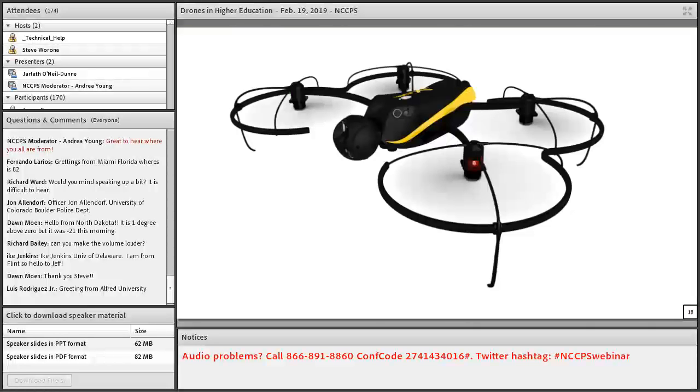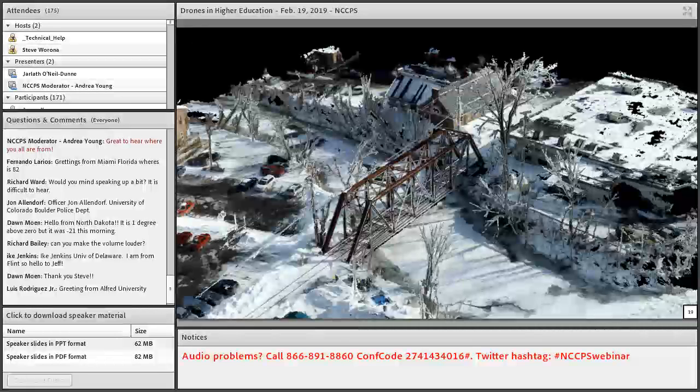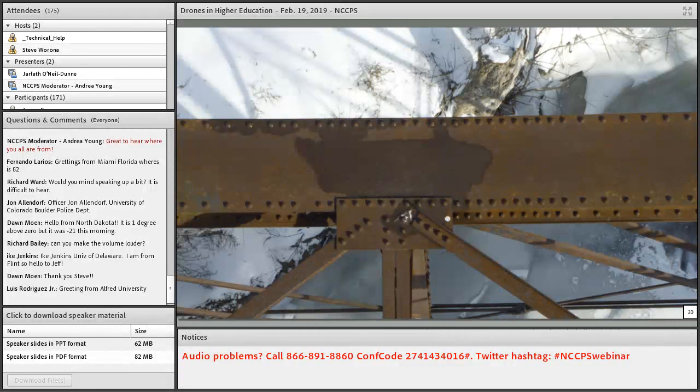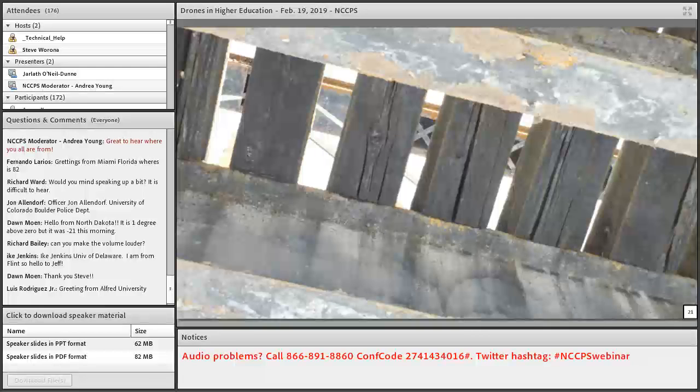The other type of drone that we generally see are multi-rotor systems. This is an example of a quadcopter here. It's got four spinning blades. It's designed for inspection, filming, and video activities. So with this, we can go out and do something like create a 3D model of a railroad bridge, such as we see here. We can also fly over that bridge and take detailed asset management images that help people understand the condition of that infrastructure. And because this particular drone has the camera mounted on a gimbal, we can also fly underneath the bridge, point up, and take a photo there.